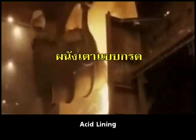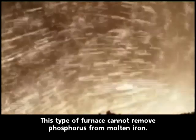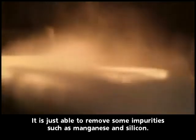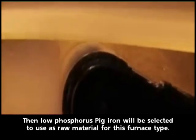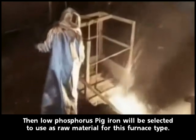Acid lining. The furnace lining material is silica. This type of furnace cannot remove phosphorus from molten iron. It is only able to remove some impurities, such as manganese and silicon. Then low phosphorus pig iron is selected to use as raw material for this furnace type.